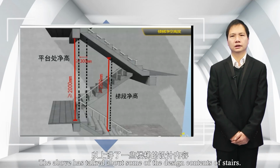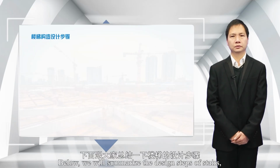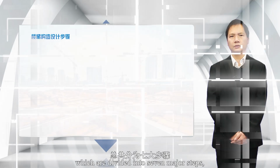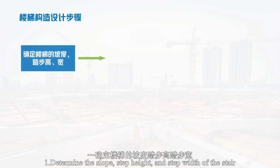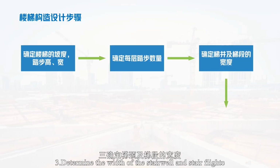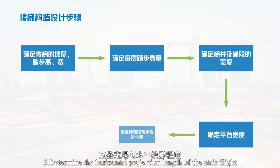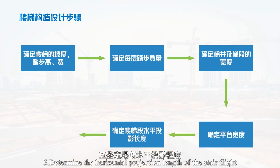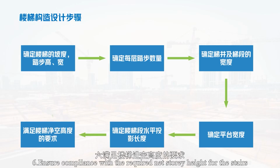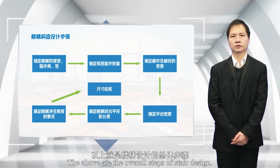The above has talked about some of the design contents of stairs. Below, we will summarize the design steps of stairs, which are divided into 7 major steps. Namely, 1. Determine the slope, step height, and step width of the stair. 2. Determine the number of steps per layer. 3. Determine the width of stairwell and stair flight. 4. Determine the width of platform. 5. Determine the horizontal projection length of the stair flight. 6. Ensure compliance with the required net story height for the stairs. 7. Perform dimensional verification. The above are the overall steps of stair design. Thank you.